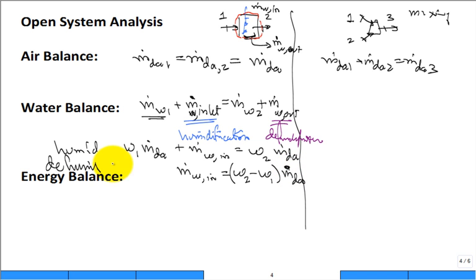And then you do it also for dehumidification. You say the m dot of the water going out will be, I come in with a high humidity ratio and go out with a low humidity ratio, omega, times the m dot dry air. So either way,